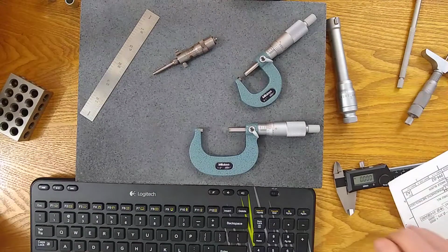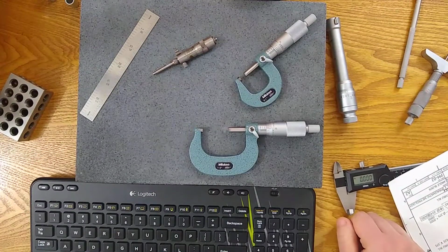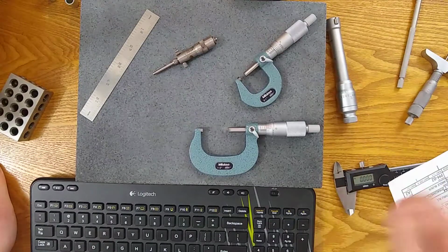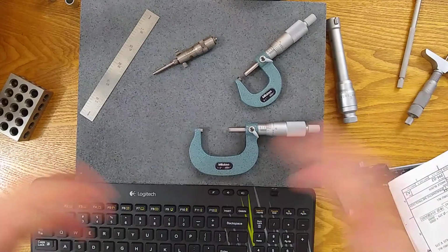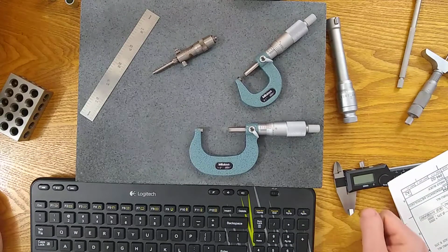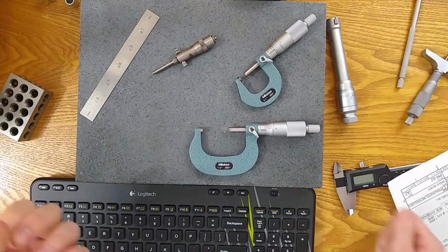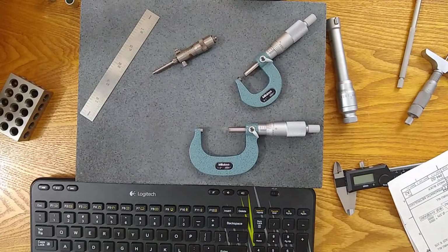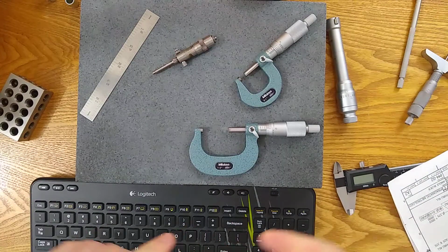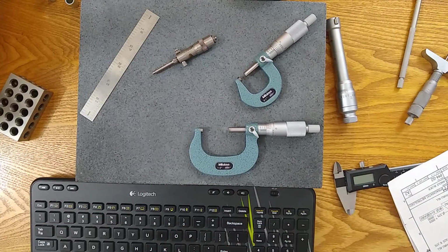So sometimes it's true, you'll get on the edge of your tolerance zone. You just have to ask yourself, okay, the gauge said I'm in tolerance, but is it still possible that the part is out of tolerance and my gauge isn't picking it up because I'm right on the edge? So number 8, once you've gone through everything, this is a continuous improvement, sort of learning opportunity. Could I do this with a different tool that is faster and maintains confidence and accuracy?